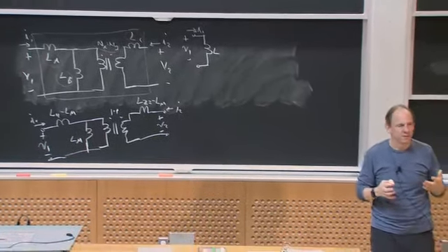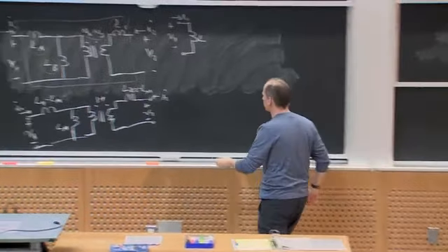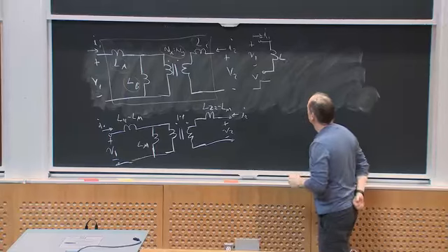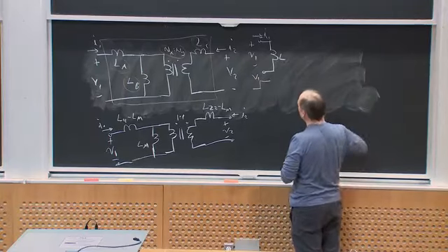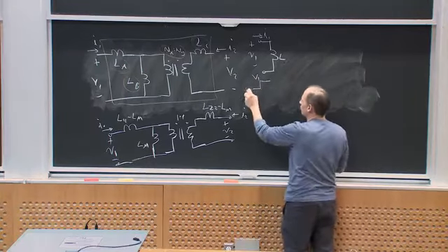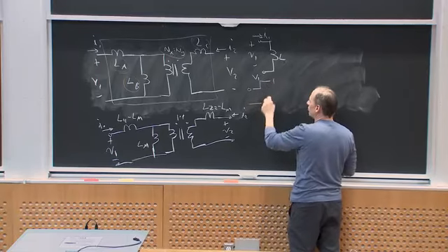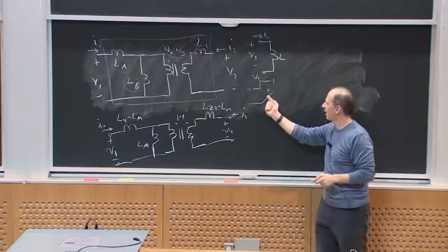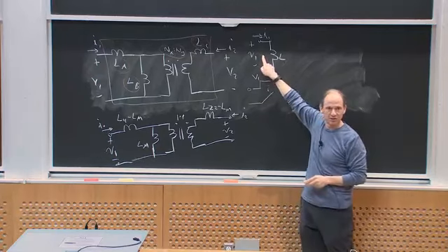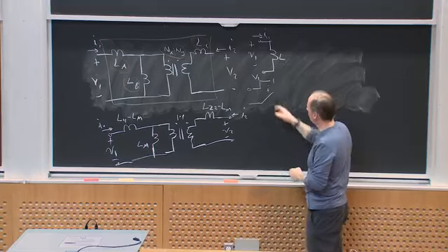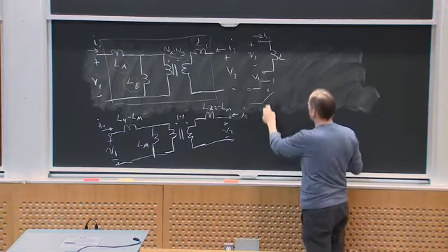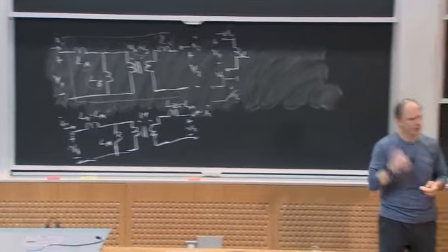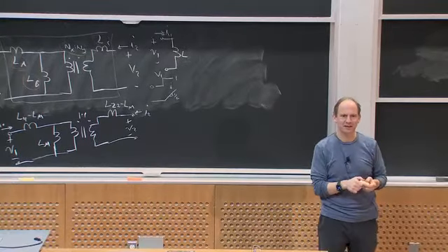Why is that? Because if I apply a positive voltage, suppose I applied a step in voltage, here's V1. What should I1 do? Well, when I step the voltage from 0 to 1, I1 should go from 0 and ramp up, right? And since V is positive and I is positive, I've got energy going into this device, right? And this slope, di/dt, is 1 over L, right? What would happen if the inductance was negative?